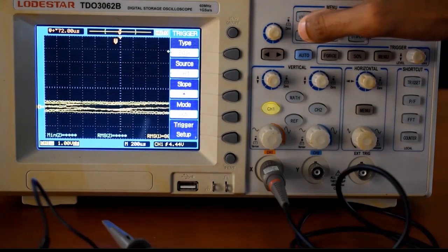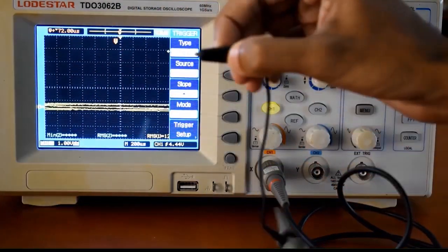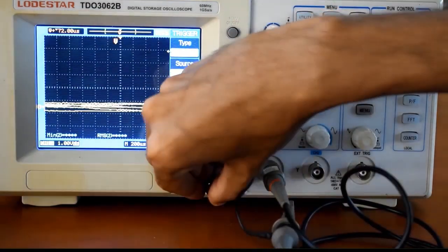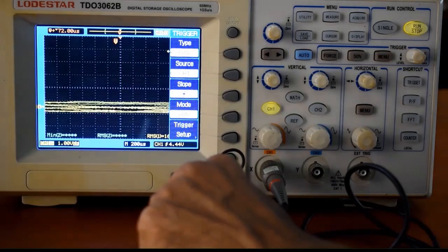Most oscilloscopes come with some kind of built-in frequency generator, so we can test our probes and tune the compensation capacitor. This one happens to have a 1 kHz square wave generator we can use. Attach the round clip to the round tab and hook the probe around the signal tab. You should see something appear on the oscilloscope's display.